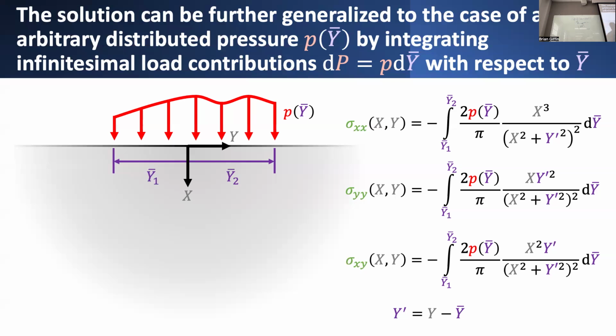The stress distribution underneath this load should no longer be infinite. The stress, in fact, should be just proportional to whatever externally applied pressure we have directly under this distributed load. So that's one way that you can avoid this problem and fix that solution so that it's not telling you that you have infinite stresses. It's not particularly useful for design purposes if you want to know the bearing capacity of some soil underneath a building, where you're trying to take that building load and distribute it over the footprint of the foundation of the structure.